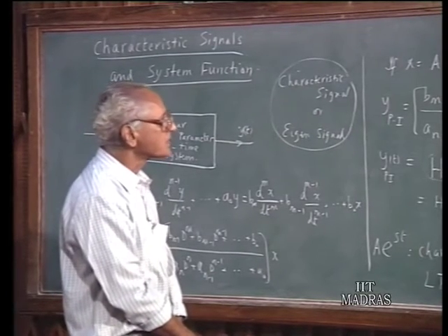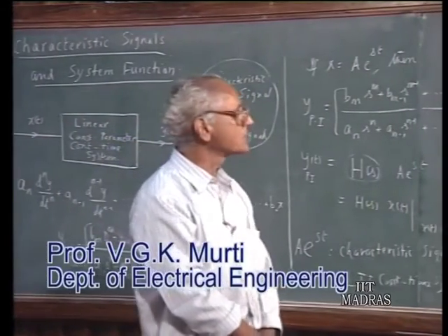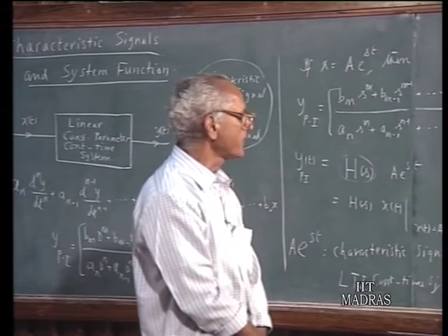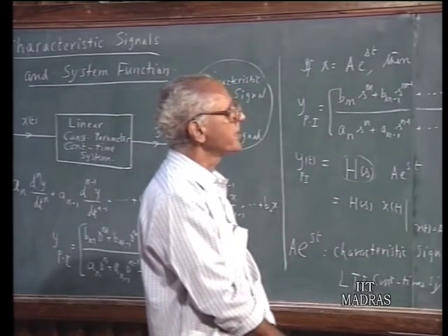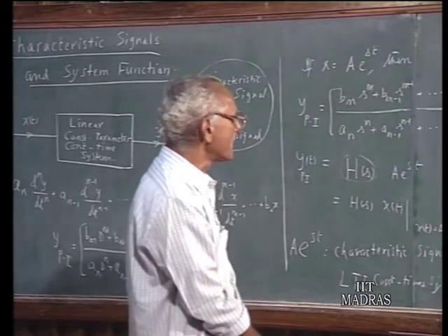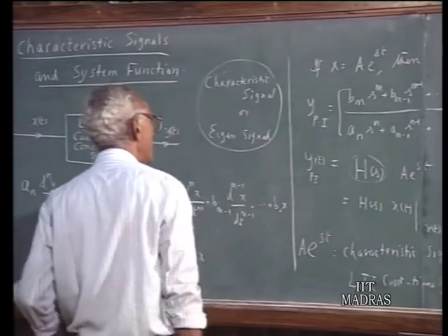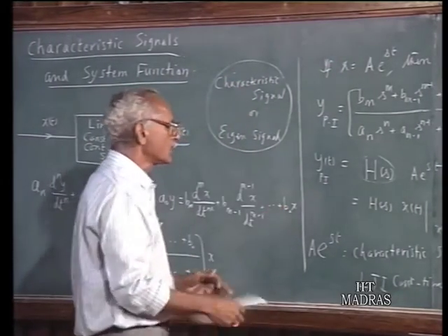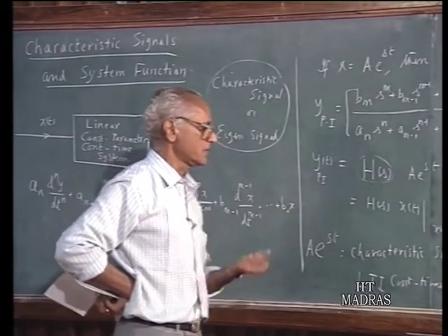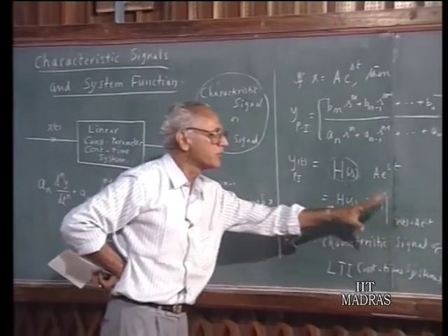Now, the system function plays a very important role in linear system studies, as we will see later, and particularly when you take up Laplace transform techniques. This system function is a very important tool in our analysis of linear systems, but it has nothing to do with Laplace transforms really. We can regard this as the ratio of the forced response to the excitation when the excitation is of the form a e to the power of st. That is all we need to know about it.